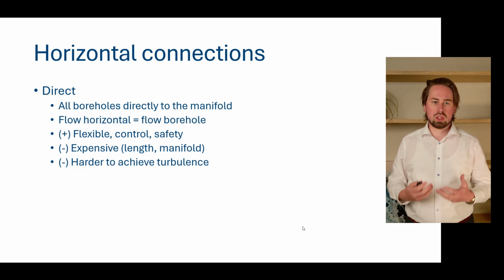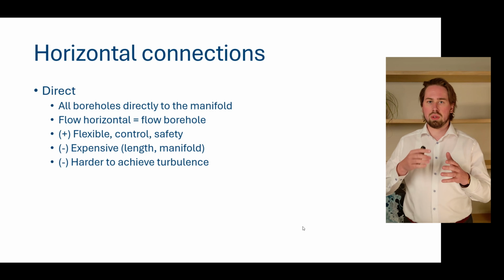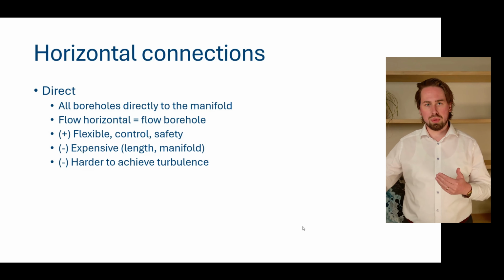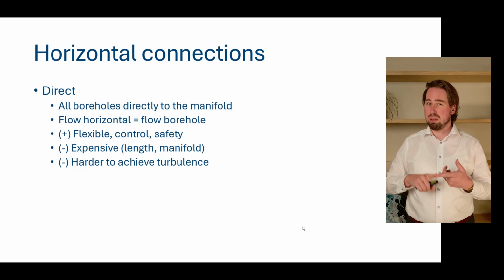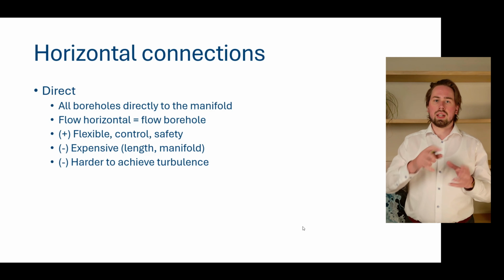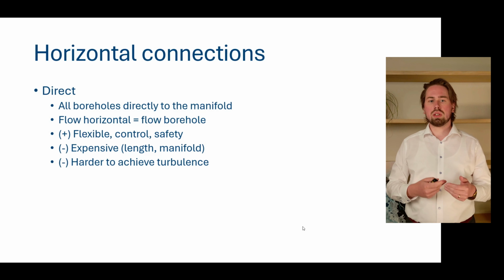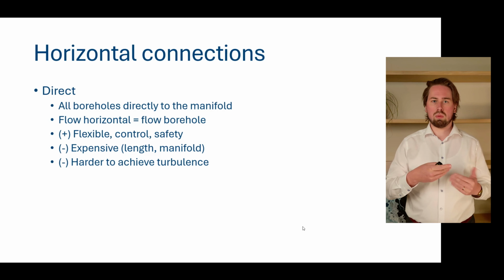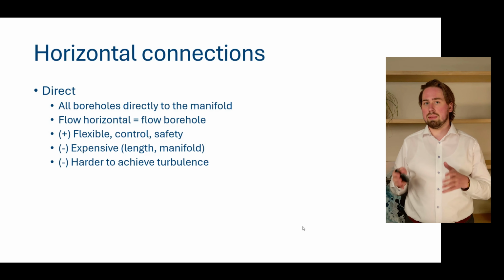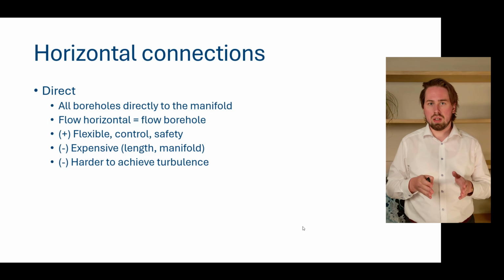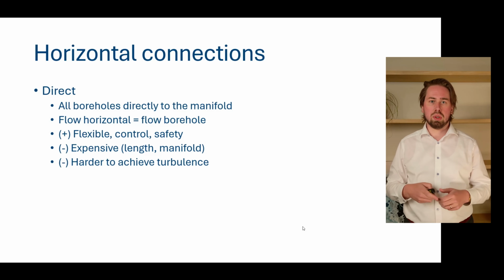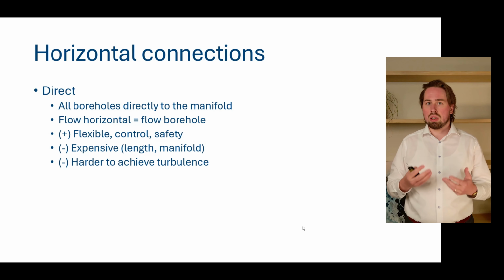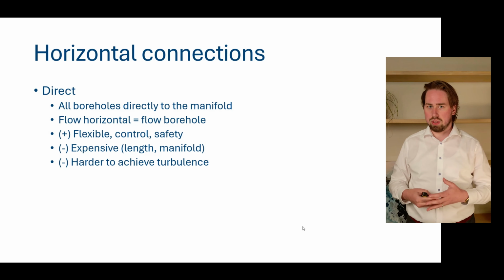The main advantage of this is that the flow of your borehole is equal to the flow of your horizontal network. It's very flexible. You have quite a lot of control since all the boreholes are connected individually. You can control the flow in each of them. It's also rather safe, because if something goes wrong with one of the boreholes, you can simply disconnect it without losing a bunch. So there are a couple of advantages of this direct connection.